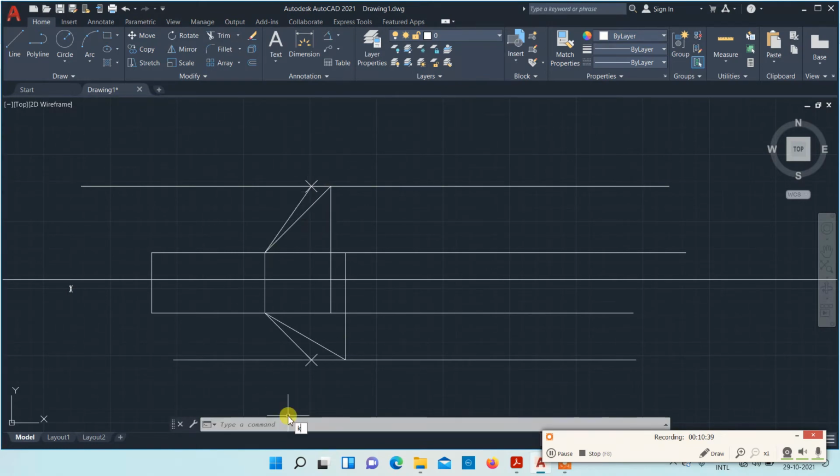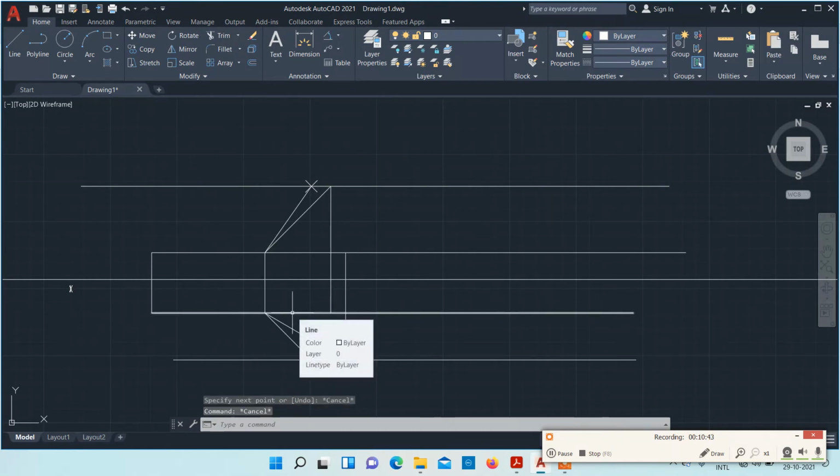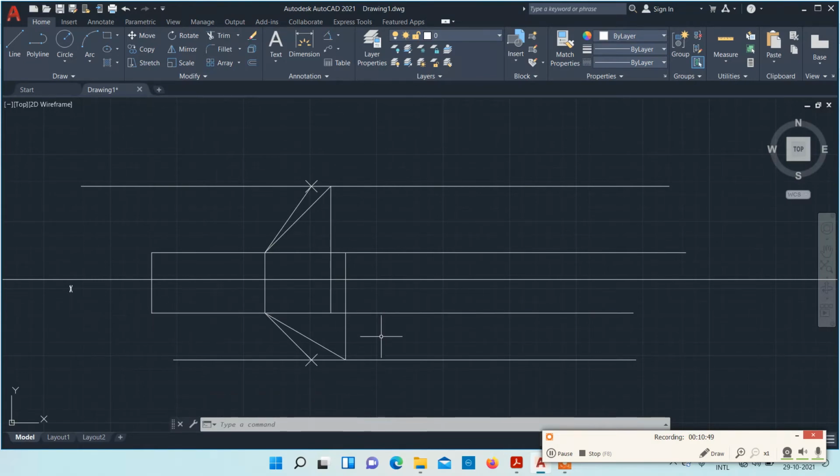You can see here. Let me differentiate the colors of the projected length from true length to avoid the confusion. Okay, then I will show you whether the endpoints are along the same line or not. So you can see that I have changed the colors of the true length as well as the projected length. Pink color lines is nothing but the true length in the top view and front view. Okay, blue color line is nothing but the projected view in top view and front view.